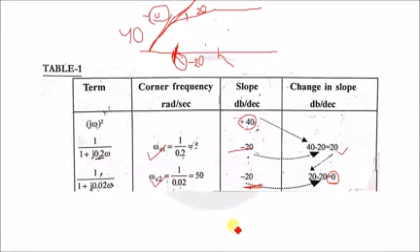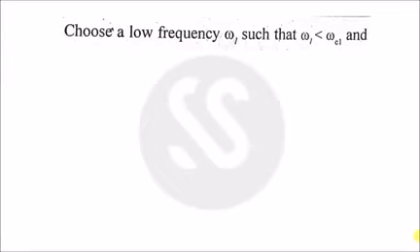So you can see that if you try to plot the graph, when my Bode plot reaches the corner frequency omega c2, after that I can predict my line will be parallel or a horizontal line. Okay, anyway, so we have found from the equation that we have only two corner frequencies, but the process says that after doing the tabulation, finding the change in slope at each corner frequency, we need to design two more frequencies.